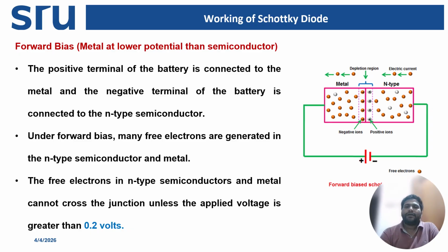In a normal silicon diode, the forward voltage drop is about 0.7 volts, but in a Schottky diode the forward voltage drop is only 0.2 to 0.3. This is because there is no p-n junction, so there is no recombination of electrons and holes at the junction. Only majority carrier movement occurs. As a result, less energy is required for current conduction. This makes the Schottky diode more efficient and reduces the power loss.